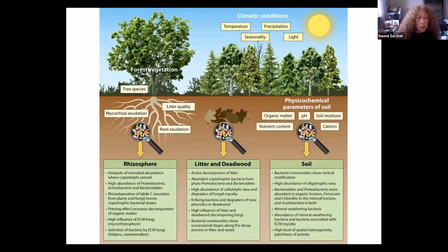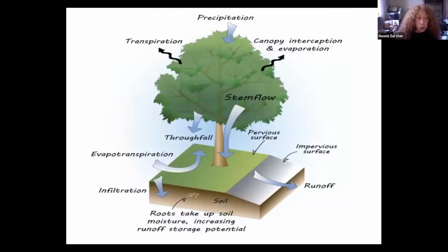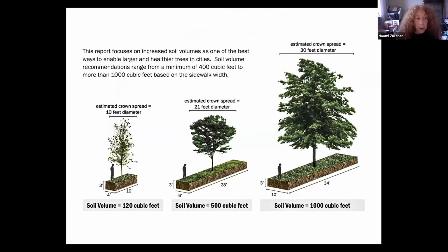biologically inactive. From an ES benefits perspective, not only is an unsealed living soil essential to tree health, it is also the foremost terrestrial carbon sink, and, in conjunction with trees' roots, an essential part of urban water management, increasing water filtration and infiltration rates, improving the recharging of groundwater, as well as runoff interception and storage. This graphic offers a direct comparison between different accessible soil volumes and the tree size each volume can support.